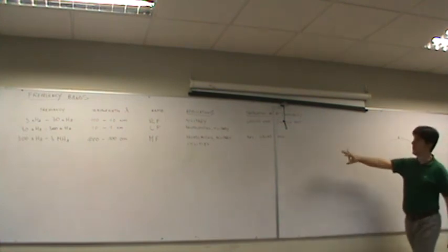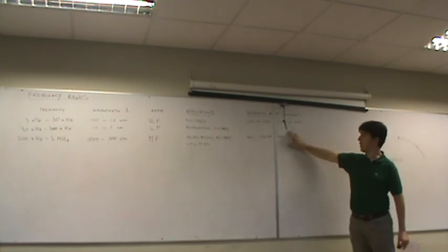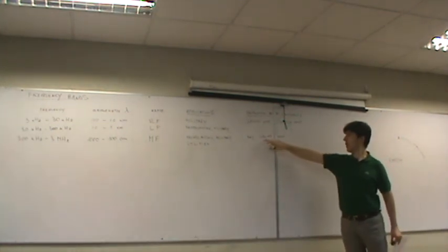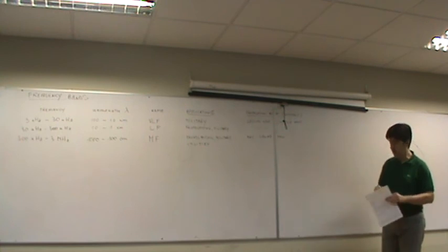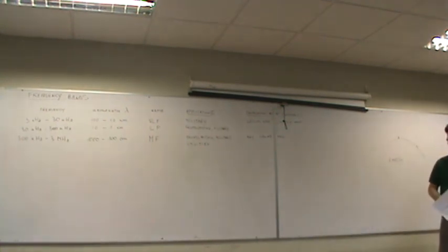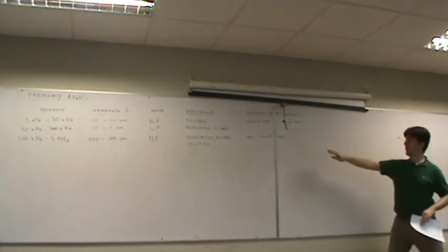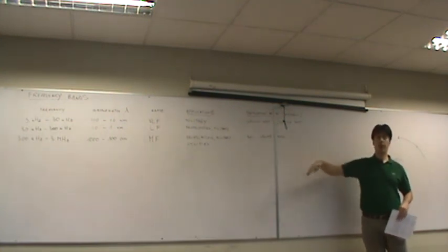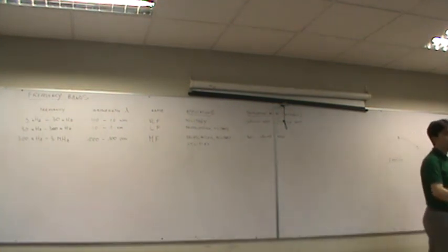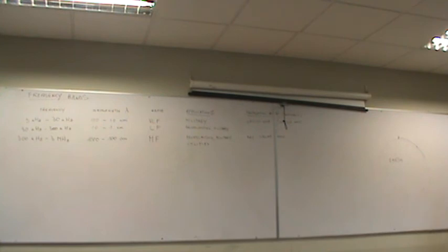So at this frequency band, the ground wave is more attenuated than at lower frequency, so the distance is smaller. With the ground wave at those frequencies, you can cover up to a few hundred kilometers, not thousands.